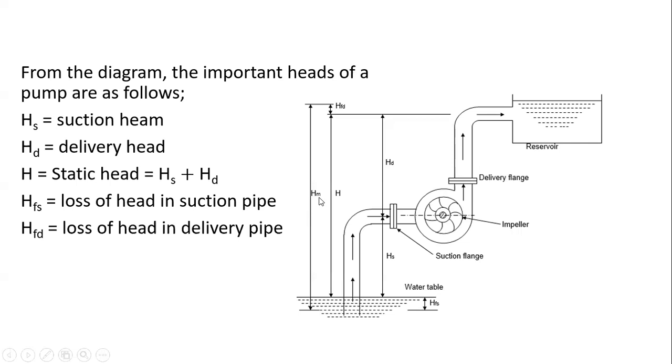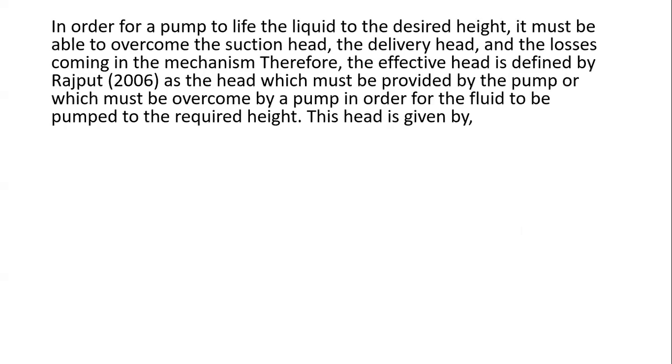But for calculation purposes, there's one more thing missing, which is the kinetic head, because when this water is coming out, it will come out at a particular velocity. So what do we do? We add it as well. Now here, this is all we have. We have this representing the manometric head, plus the additional, which is V squared over 2g.